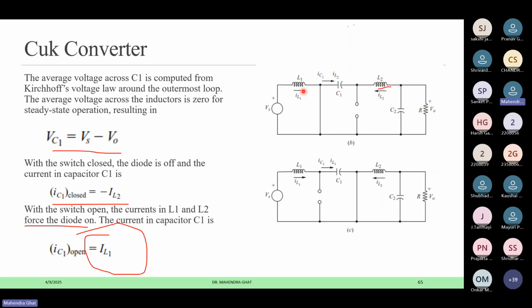They are storing the energy and releasing the energy. Whatever energy is stored, that much they release. They are the passive elements. From the operation point of view, over the cycle there is no net charging or discharging of that inductor or capacitor. If we replace this with the battery, then also in on time you are charging the battery and in off time you are discharging it.